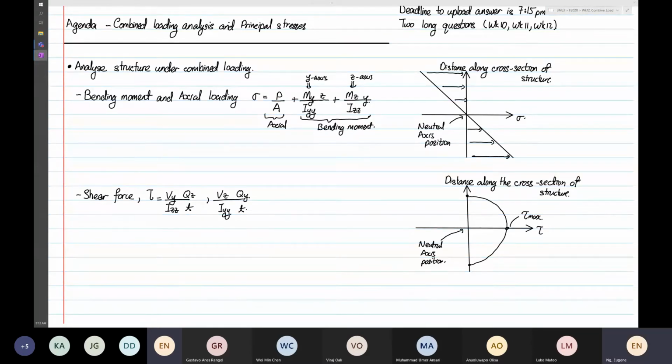Whereas the bending moment max, you can see, is over here. So this is positive, and this is negative minimum, right? So when you design your structure, where will you use? Do you use the neutral axis where you have maximum shearing stress, or will you use the bending moment, which is furthest away from the neutral axis? So which one to use, I will cover in this topic. This is where it's interesting now down here.